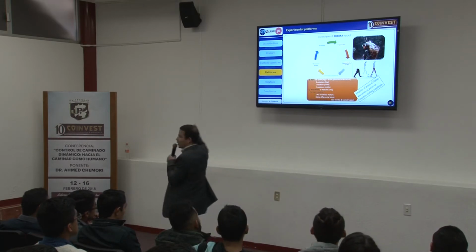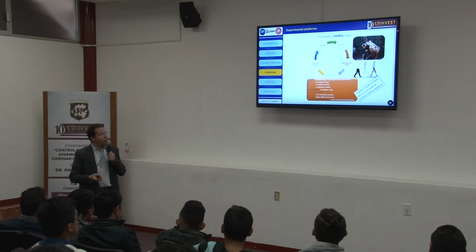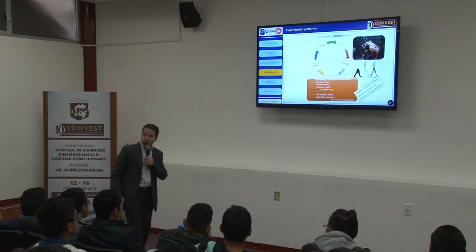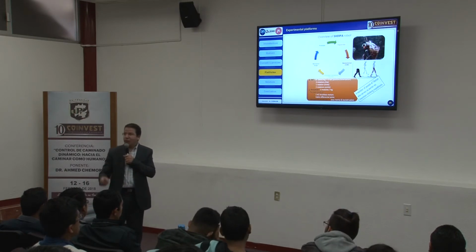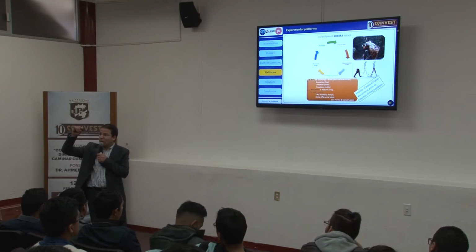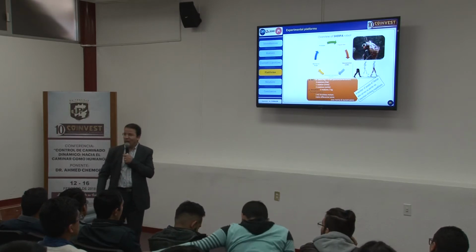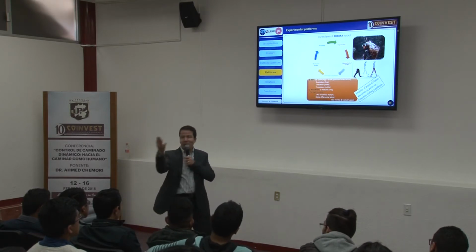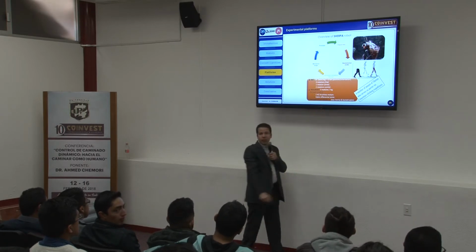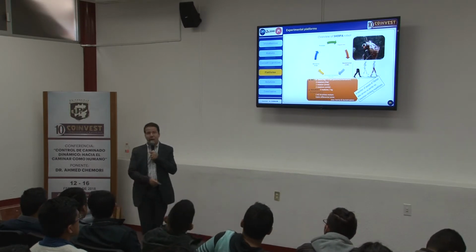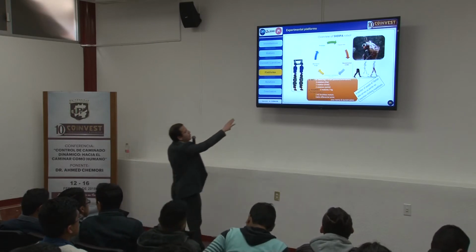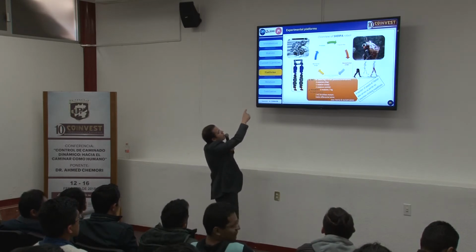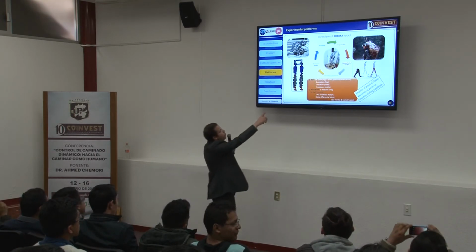And why do we propose back drivable actuation for the robot? If you look at human walking, during the swing phase we give a very, very small amount of energy. What we use is the gravity. We use the gravity and we swing the leg based on the gravity. So we try to reproduce this with this kind of actuation on the robot. This is the idea. Now, this is the result of the mechanical design of the robot, as you can see. We have constructed mechanical parts here without the electronics, and the final prototype is here.